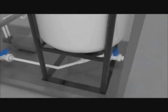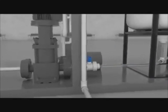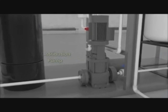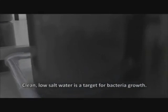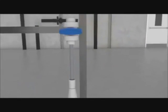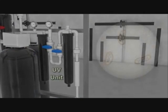The product water is fed from the bottom of the tank to the distribution pump, where it will be post-treated before being fed to the facility points of use. The clean water low in salts, typically stored for a period of time, is a target for bacterial growth. Therefore, the process and water system includes a germicidal ultraviolet disinfection unit for bacteria control.